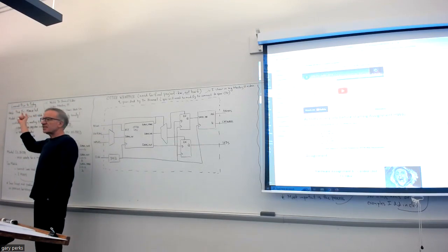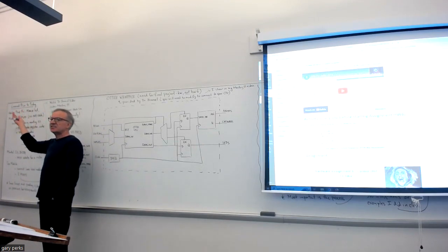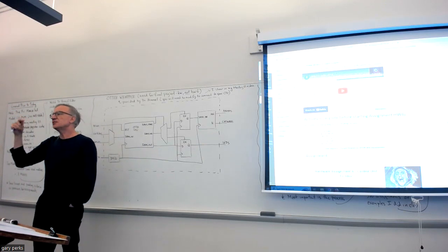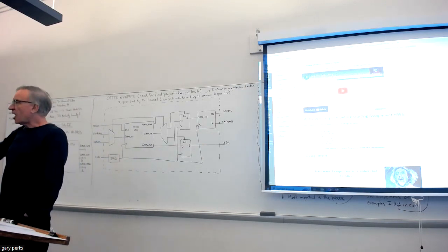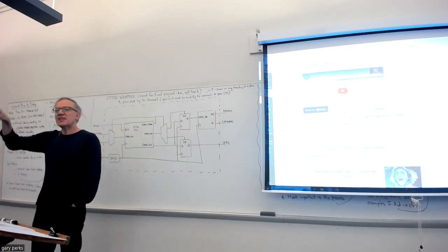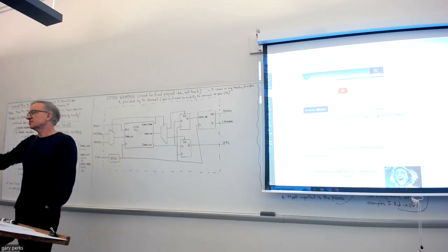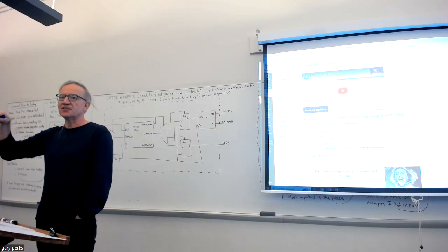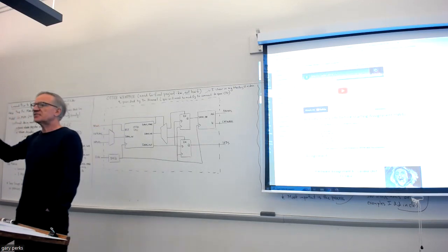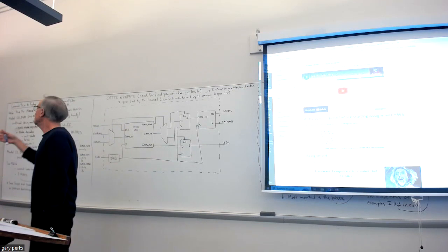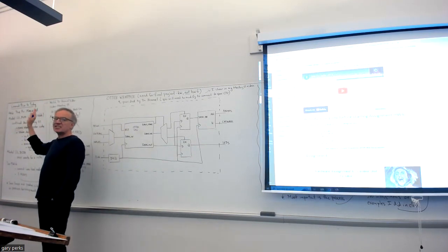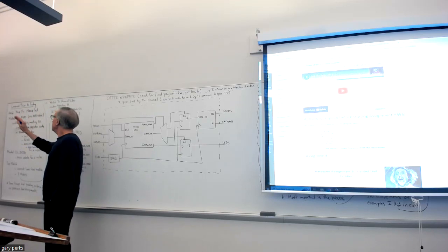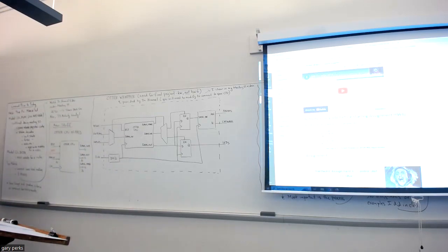So for hardware 6, your FSM doesn't need a write back state, because you just want your Otter CPU to run that program that has 6 instructions, the same program that I had you do the activity timing diagram for. Since none of those 6 sample instructions are load instructions, the FSM does not need a write back state.